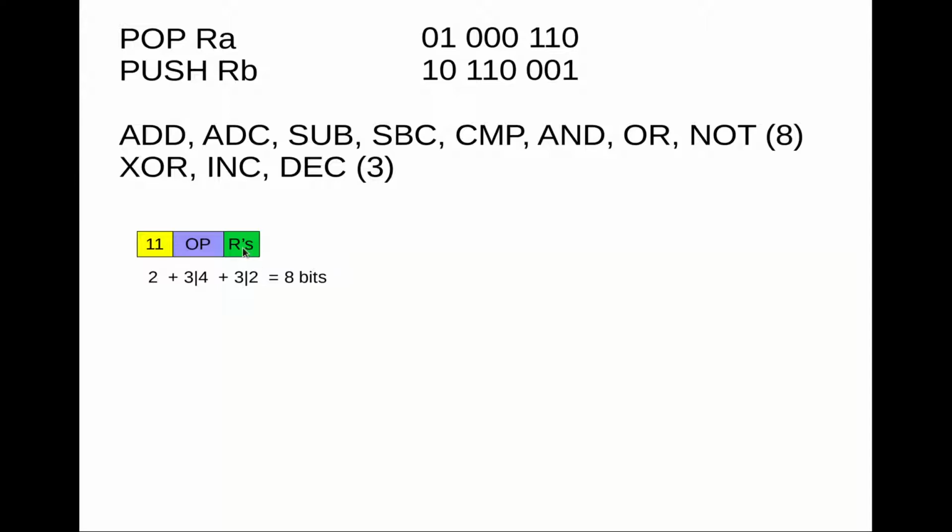And so in the case of this CPU, because we're using opcodes which are only 8 bits long, we can't really encode 2 different register values in here. And so we could either make our ALU instructions longer, make them 2 bytes wide, but that would make our control logic an awful lot more complex, because then we'd need to start dealing with varying instruction lengths. And up until now, all of our instructions have always been exactly 1 byte in length. And so the loading cycle has always been exactly the same.